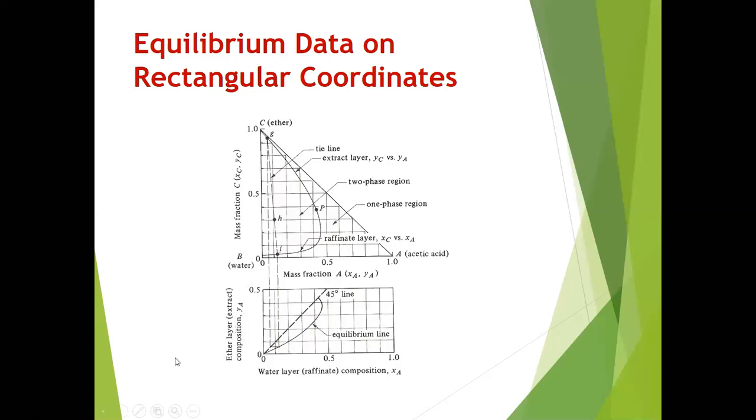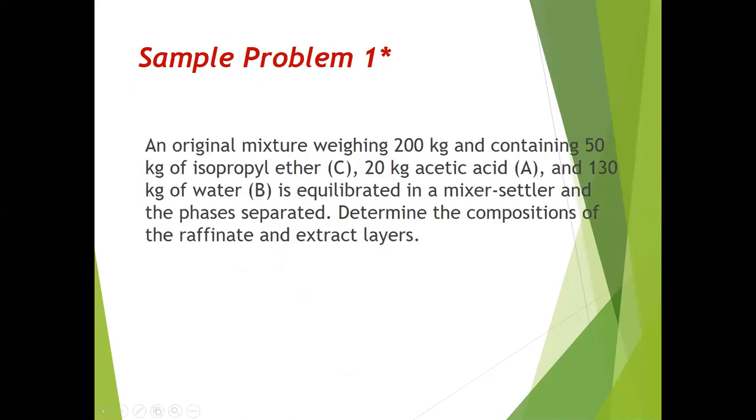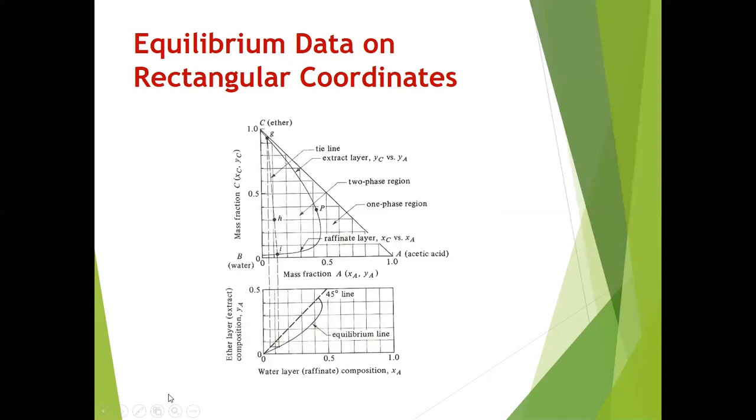So in that case, we will have to find the 29.5 weight percent acetic acid in this case. So now, let me try this if I can write. You need to place in here the 0.295. You find this is 0.5, this is 0.4, this is 0.3, this is 0.2, and this is 0.1. Your 0.295 is very near 0.3. So let's say this would be that thing. I'd like to label this as L1. I have a difficulty writing there. This is L1.